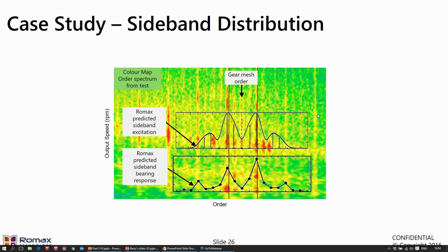From the concept tool, can we find a design which will cancel main mesh as well as sidebands for given errors? Yes, you can. You can look for those. Typically, you can't do that with 3 planets. You need at least 4 planets to do that. Typically, it's done with 4 planets. And usually, it also means having unequally spaced planets.